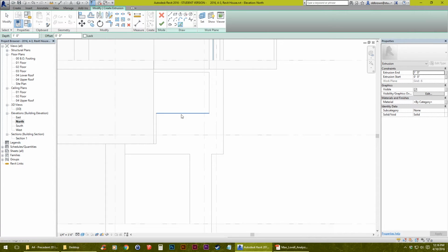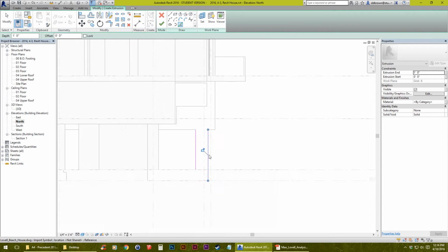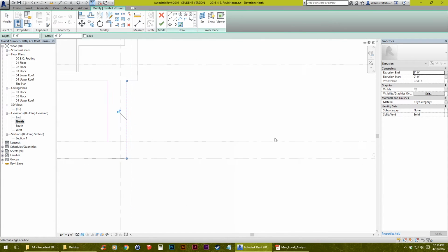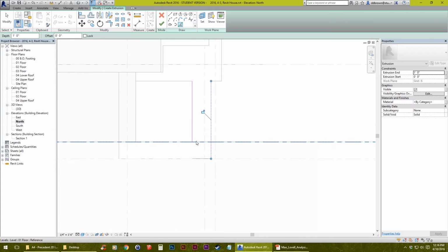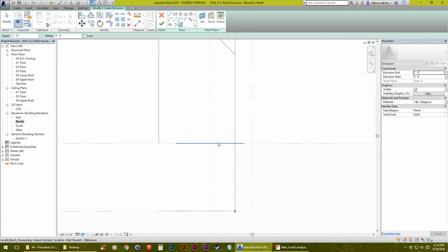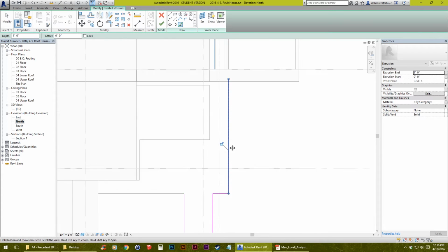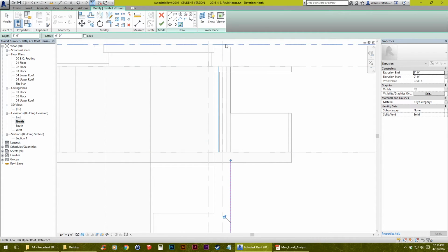So I'm going to use my Pick Lines tool, and then I'm going to pick the different lines that make up this column. You can see our first floor starting at the 0, so I just want to click on basically this line between them. You can use Tab, and that'll cycle between, say, different overlapping lines. So I'm going to pick these lines here. This one will run all the way up to the top, and then it will run back down.